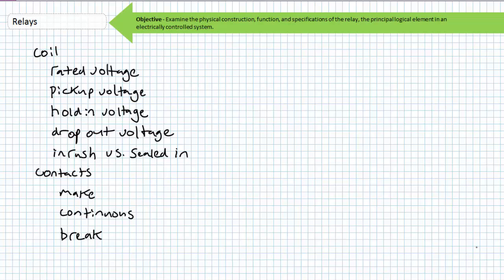Finally, given the coil's operating principle is that of magnetism, when current through it ceases, the magnetic field collapses in an effort to keep current traveling in the same direction. This sometimes results in a voltage spike that can damage equipment. Sometimes the means of suppressing this voltage spike is included internal to the coil or must be externally attached to it. As mentioned previously, DC coils with suppression means are polarity dependent.